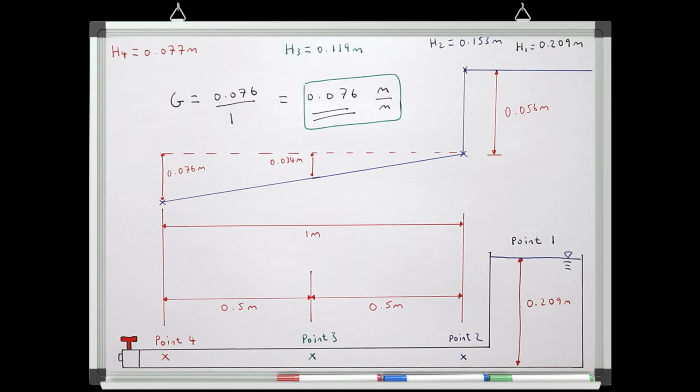In the system that we're looking at the moment, the energy that we've lost due to local losses is fairly similar to the energy we've lost from friction and turbulence. However, if the pipe was 100 meters long, then the losses due to friction and turbulence would be massive compared to the local loss, and we could probably neglect the local loss from our calculation.